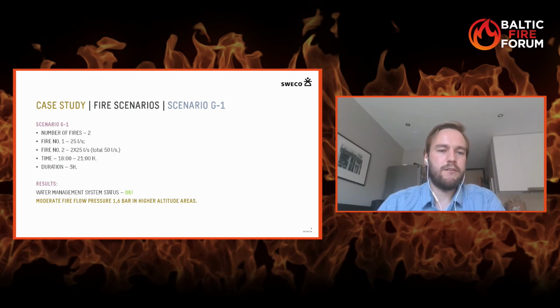And I will quickly give you a few sentences about the results. In this case, the water management system status is okay, and there are only some moderate fire flow pressures in higher altitude areas, about 1.6 bars, and that is okay, I would say.